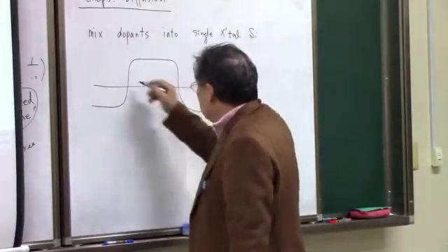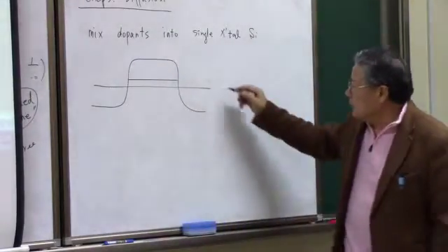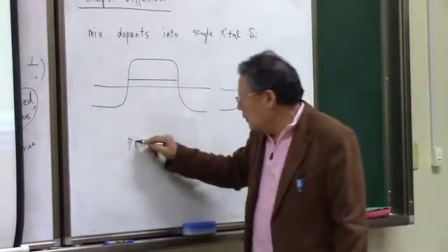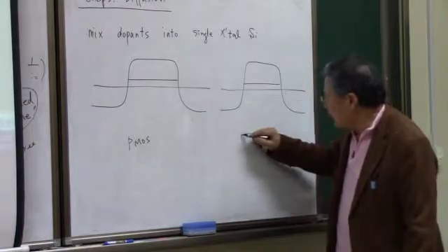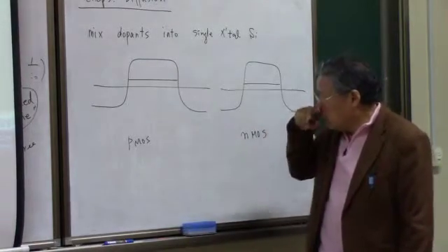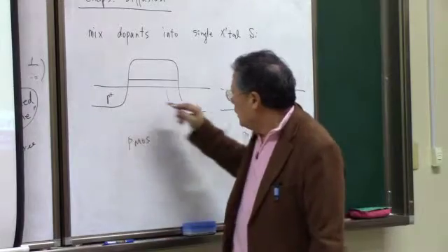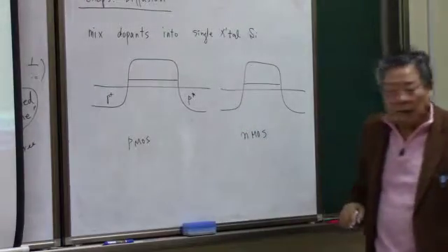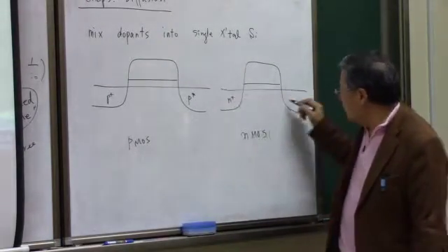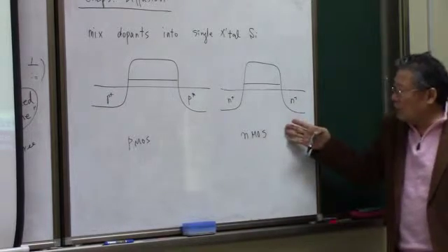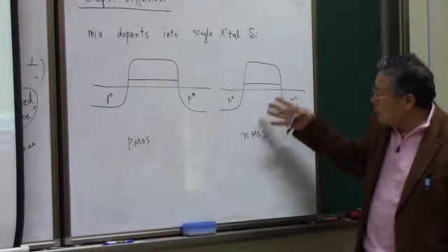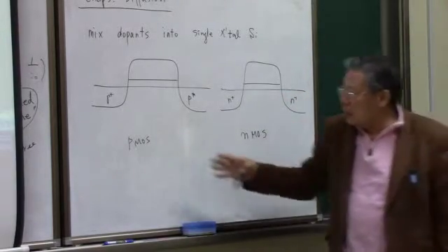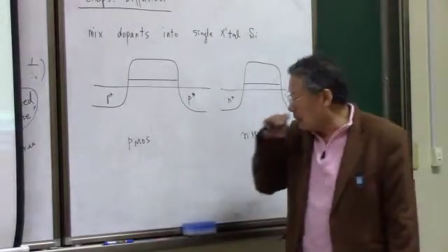Like this is a MOS structure, and then we can have PMOS, P-type MOS, or N-type MOS. Okay. Then P-type MOS means the source and drains, we have heavily doped P+ regions for the source and drains like this, and NMOS is N+ like this, so that electron is basically used for the operation of this transistor, and holes for the PMOS.